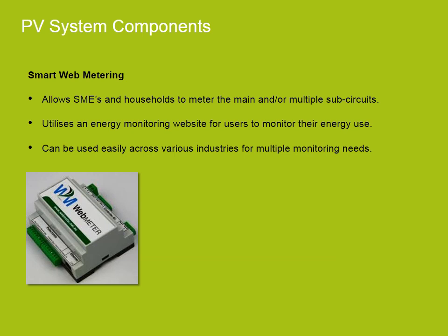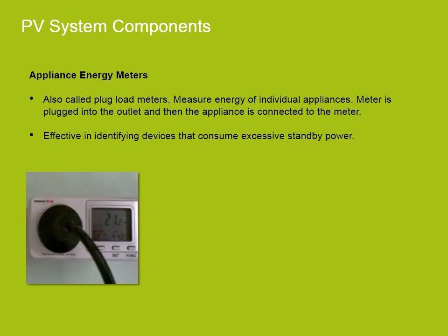In addition to measuring energy used, electronic meters can also record other parameters of the load and supply, such as maximum demand, power factor, and reactive power used. They can also support time of day billing, for example, recording the amount of energy used during on-peak and off-peak hours. Smart web meters can be fitted to main or multiple sub-circuits, allowing them to report on any level of information required, though obviously the more circuits it is fitted to, the more detailed the information reported, and the more opportunity for efficiency.